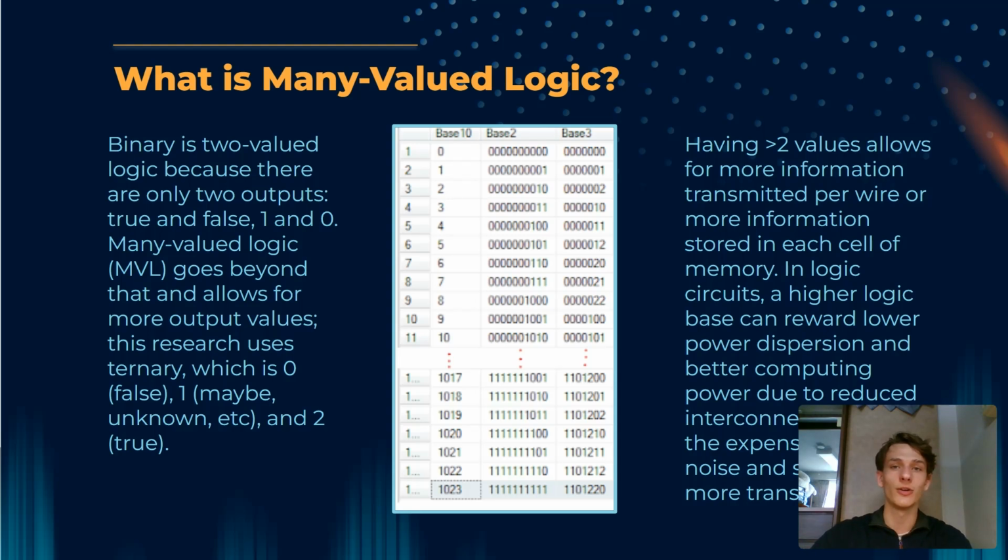This is different at an electrical level. It's all nanoscale in these circuits, and in binary, 0 is your ground level and 1 is your supply voltage. While in ternary, 0 is still your ground, 2 is now your supply voltage, and 1 is half your supply voltage. Also meaning that you have to read at half the potential differences for ternary, which is much harder, but can be worth it.